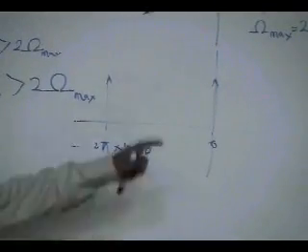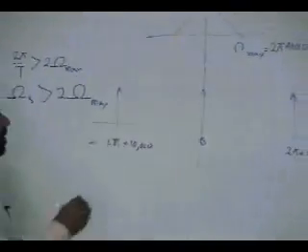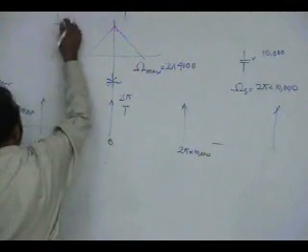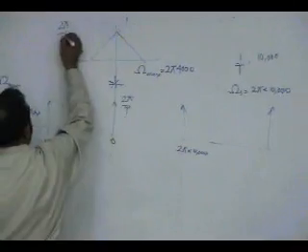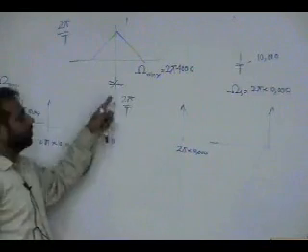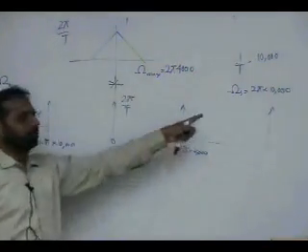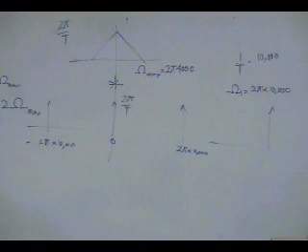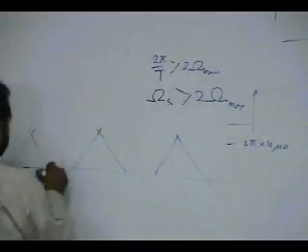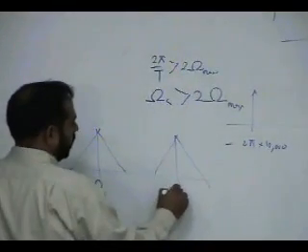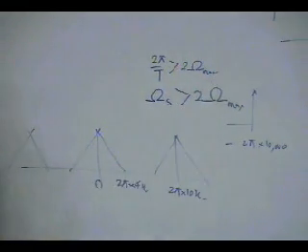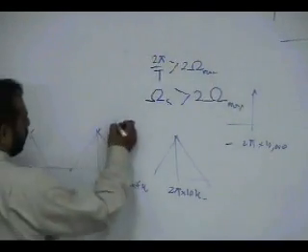So this is the step where you make this, and this magnitude is 2 pi over capital T. Now you convolve them and divide them by 2 pi, remember, 2 pi by T. So this convolution will make a copy of the signal at the location of these impulses. If you draw this, you get a signal here, a signal here, a signal here: at 0, at 2 pi into 10k, at 2 pi into 4k. That's what you get. And here you will get 1 over t.